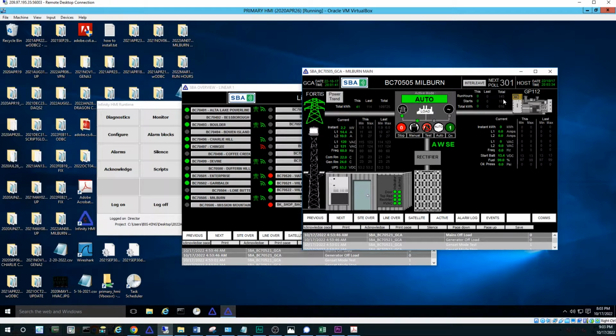This can be useful in determining maintenance intervals, troubleshooting technical problems, or verifying that repairs have been successful. Under the generator, we have current values outlined in green for instantaneous kilowatt hours, amps on line 1 and line 2, voltages and frequency as well. We have included our start battery voltage, as well as our fuel level and oil pressure.